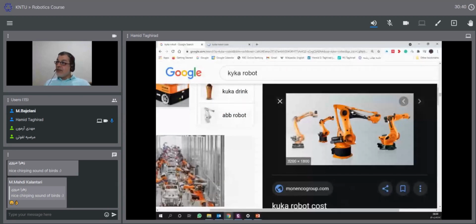As you see here, we have two links here, one here and here. Again, here we have a parallelogram. You have that in your assignment as well. And since you have a parallelogram, you can use a counterweight in here, or use an electromechanical or some pneumatic or hydraulic cylinder here to compensate for the weight.